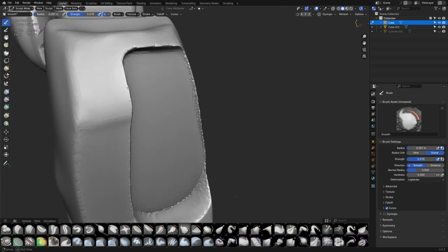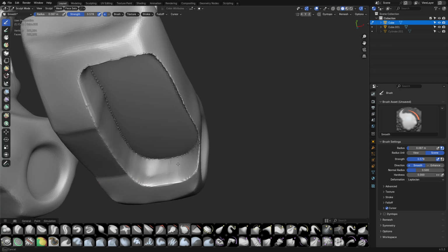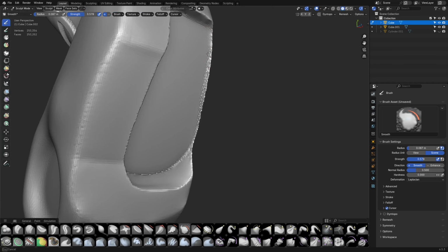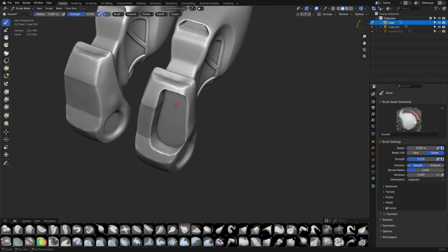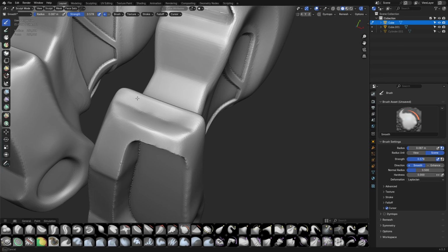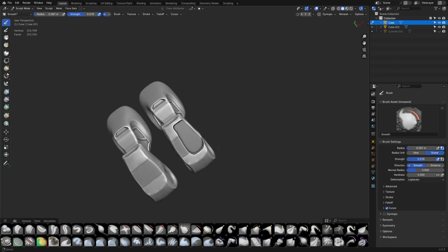There's a couple different methods, and something to think about, right? Doing it manually, though, is not the end of the world. Just do it lightly and get it all worked out, you know? Try not to create little lumpy surfaces and stuff like that. And that'll help you during a retopo process if you're going to retopo this. Usually retopo, you're not going to use a shrink wrap. Like you could if you wanted to, but it doesn't make as much sense with this kind of a sculpt because it's just not high detail. It's not super smooth, perfect surfaces, so you're not going to use it in that manner. You're going to just go around and just retopo it by putting some mesh on top, and then you'll go through, and if you turn it into subdivision mesh, you'll use either creases or holding edges, those kinds of things. And you can start to work these kinds of things out in those manners.